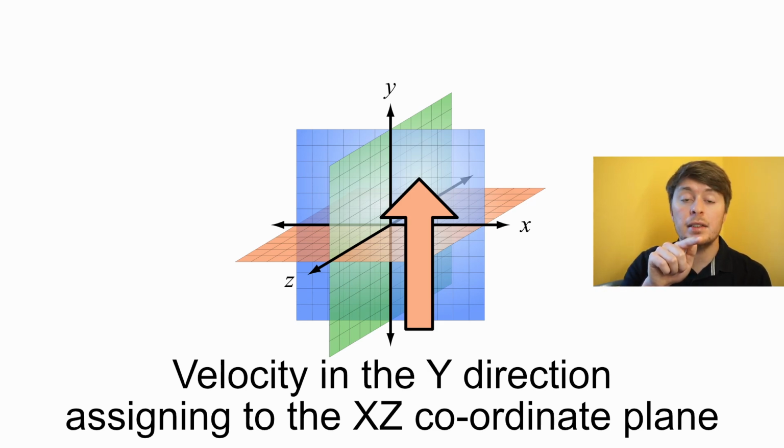If the X is 50%, so in the middle, and our Z is 50% in the middle, we would expect it to be the maximum velocity. Whereas if it's on the edges and the corners of this imaginary rectangle inlet, we would expect them to be dropping off by 4 times the amount, as a basic parabolic curve suggests.